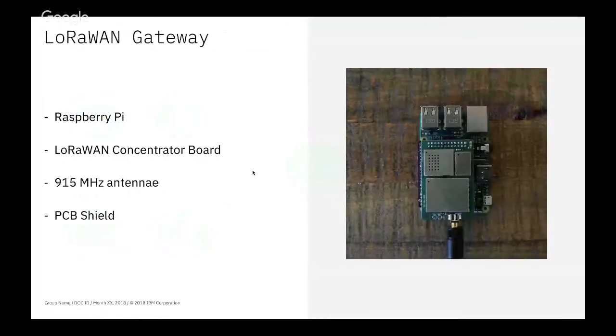All right, starting with the hardware, the first step was to assemble a LoRaWAN gateway. This is basically the central connection point for all incoming sensor data, so it should be in a secure location, somewhere that has both power and internet connectivity. I assembled a gateway by adding a LoRa concentrator module and an antenna to a Raspberry Pi. I also had to install some open source software called LoRaWAN Server on it. The end result is shown in this picture.